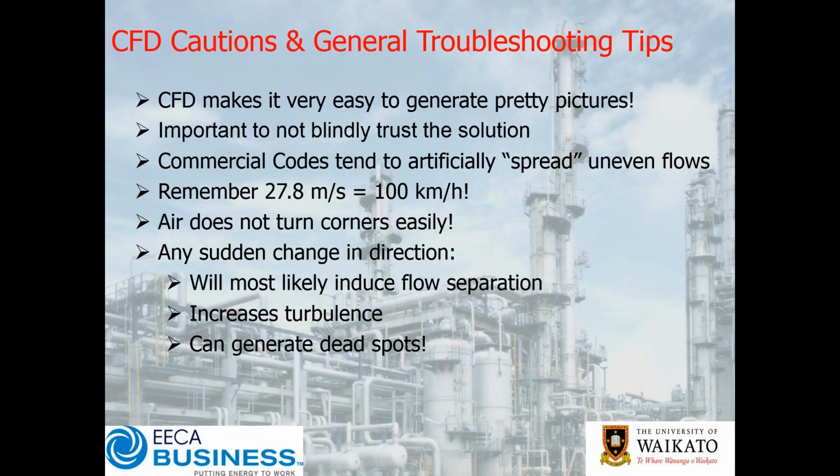As we've just shown you with these pictures, it's very easy to generate some pretty pictures, but it's very important that you don't blindly trust the solution. I could have equally set those models up, put some back pressure across that plate and delivered you a nice even distribution of airflow. Now we know that that doesn't actually happen in practice, and the reason for that is